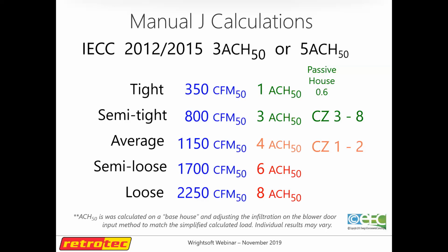Yep. And sometimes as you get into it, you can guess and maybe get it close. But honestly, if it's an older home or if it's a home with some complicated details on it, you don't know until you test it. And so that's how you can use your blower door to make your load calcs a lot more accurate. Yeah, particularly the further down you get, right?